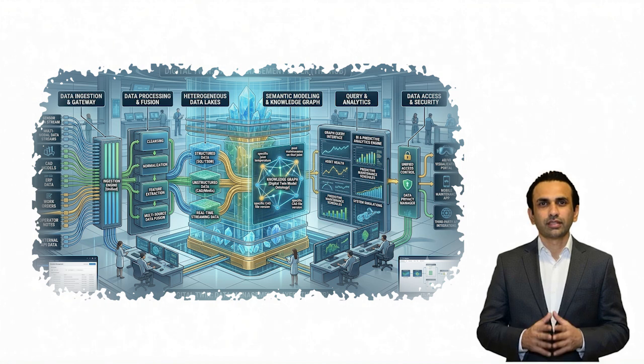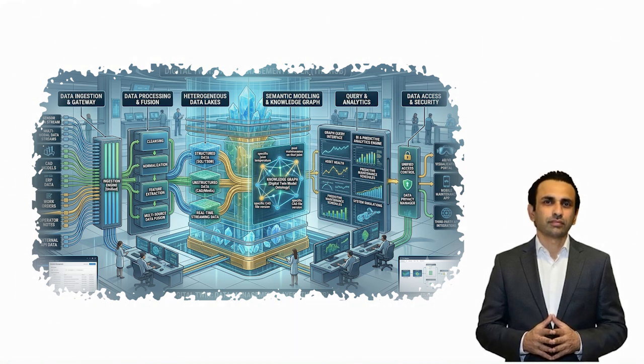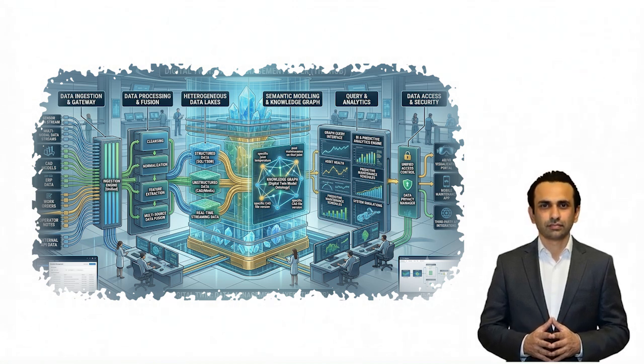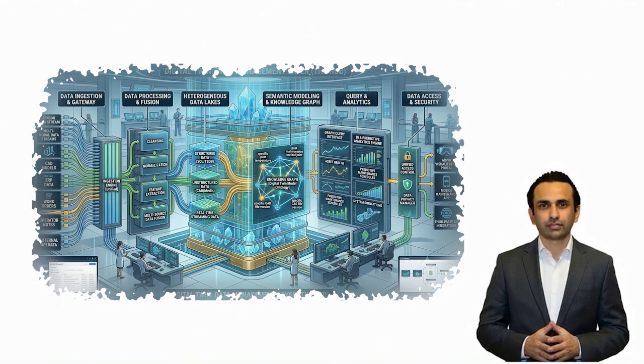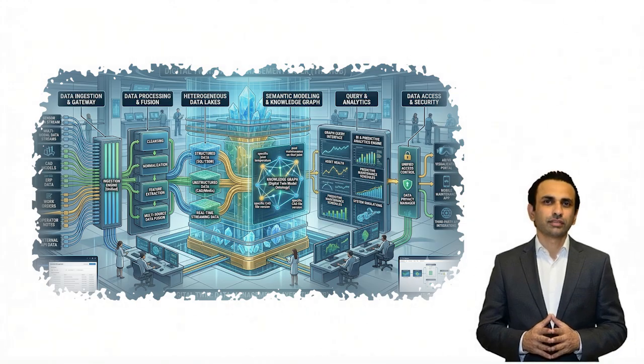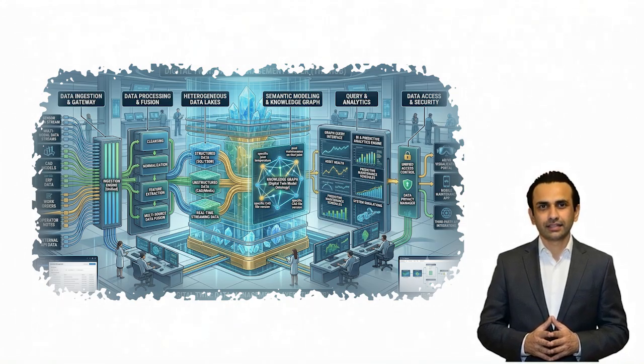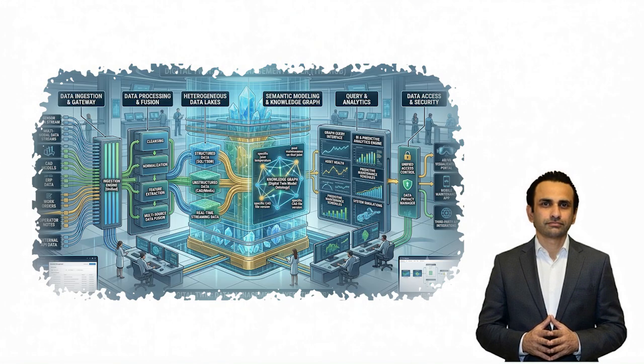Layer 4, Data Management layer. Now we enter the data management layer, one of the most critical and underrated layers. This is where data is stored, organized, modeled, contextualized. Key responsibilities include time series storage, asset hierarchies, metadata management, data quality checks.